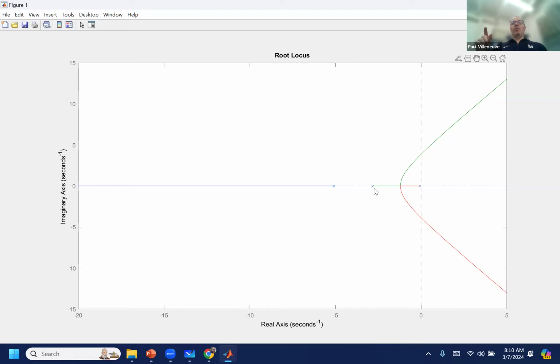So you do a root locus, you start at a pole and you end at a zero. So you can see here, I'm starting and starting. These are X's, those are poles. Over here, there's an X, and you can see I stay on this real axis. That's because there's a zero way out at S equals infinity. What about over here?